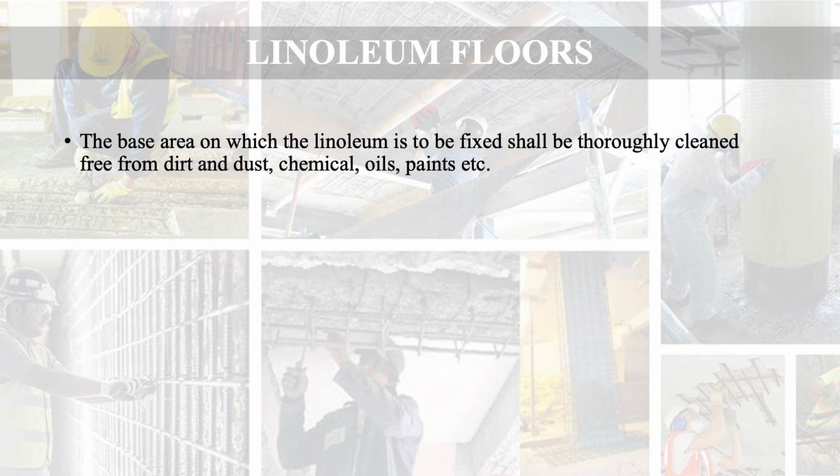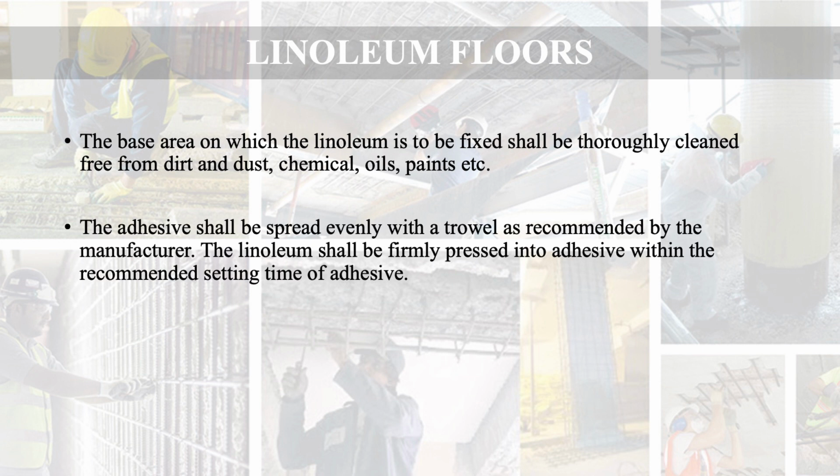The base area on which the linoleum is to be fixed shall be thoroughly cleaned free from dirt and dust, chemicals, oils, paints, etc. The adhesive shall be spread evenly with a trowel as recommended by the manufacturer. The linoleum shall be firmly pressed into adhesive within the recommended setting time of adhesive.